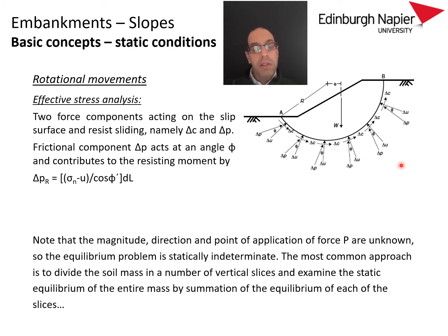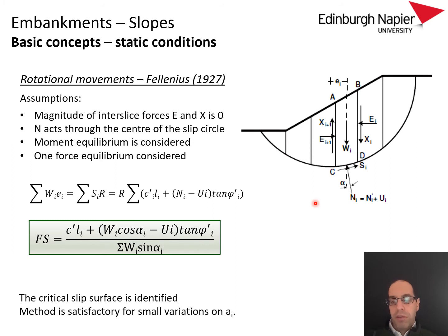If we do that under long-term conditions, the principle is exactly the same, but what you quickly realize is that you have more unknowns than knowns, and that you need to start making assumptions to solve the problem. And it is at that point that the methods of slices appear, that I'm sure you remember. This is the first of the methods that you see during the fourth year, the Swedish method or Fellenius's method. And as you can see, it is expressed here in terms of long-term conditions. But the principle is the same.